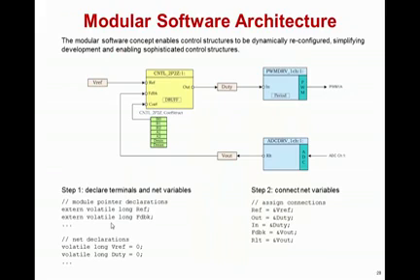The C2000 microcontrollers are supported by a digital power library, which we can represent using this module diagram shown here. The yellow blocks represent functions in the library that are purely computational, such as our control law computations. The blue blocks show any type of function that interacts with the module or a pin. So the PWM shows how we can take a variable, in this case duty variable, and output that on our PWM 1A channel.